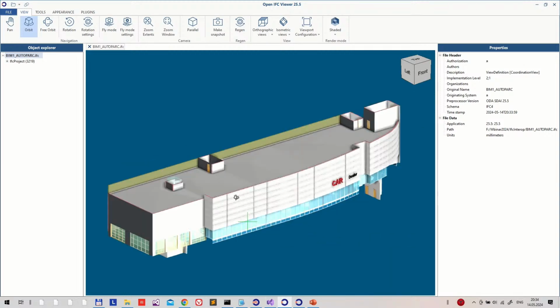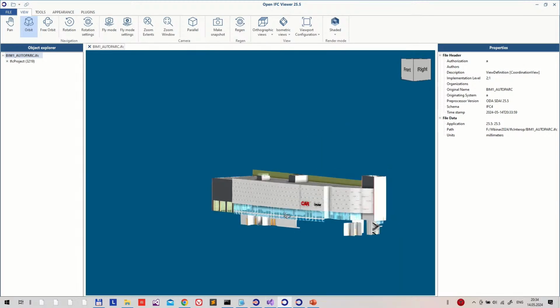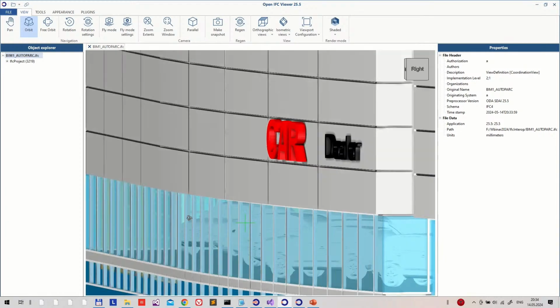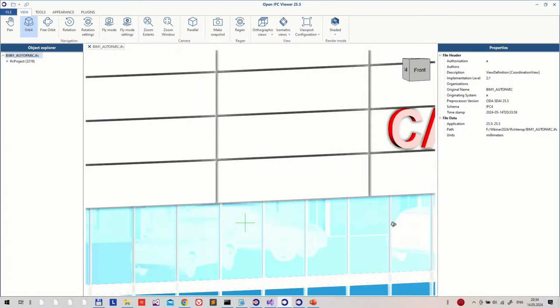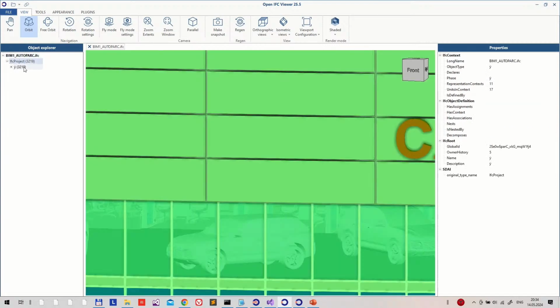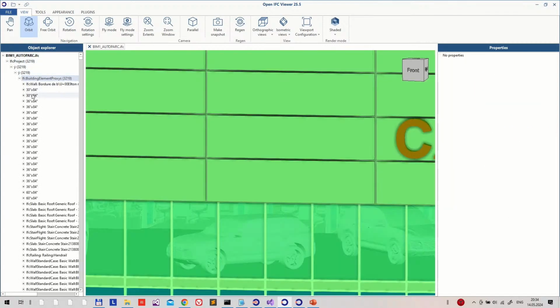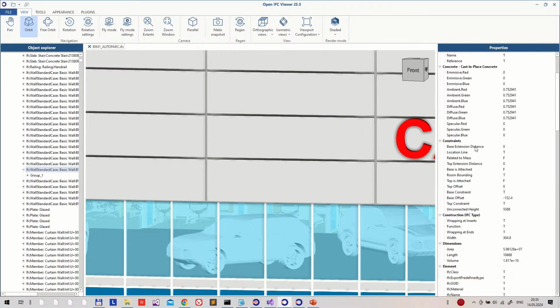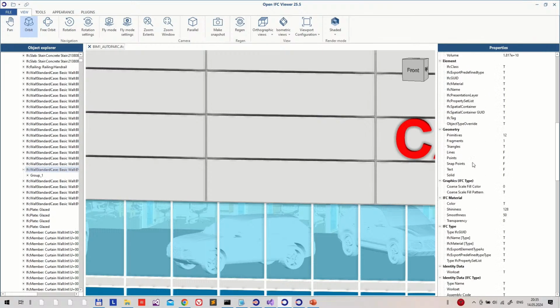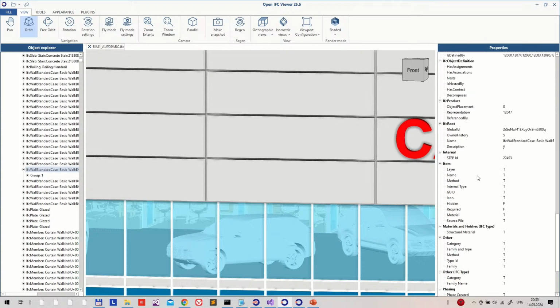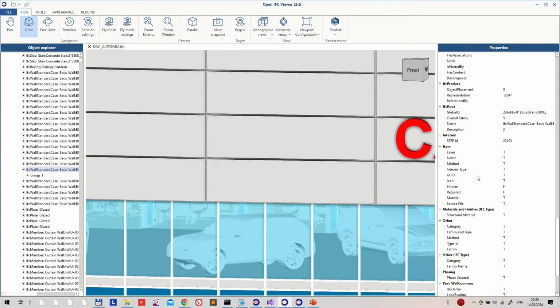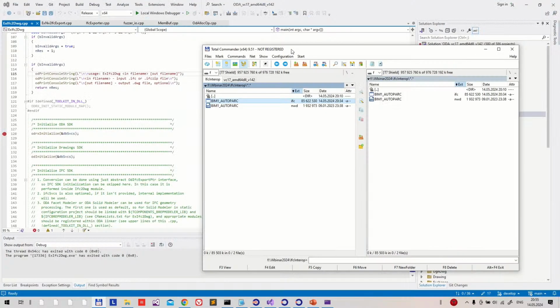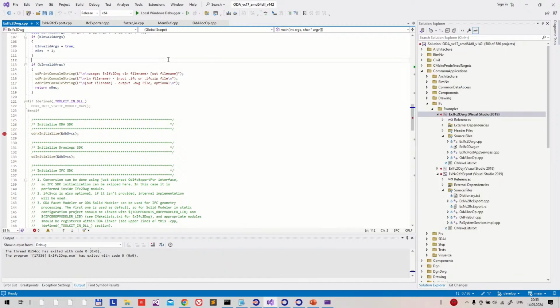That is what we received for the IFC model with the current implementation. As you see, those are not just geometry primitives in IFC or some primitive elements. Those are complex elements, and what's more important, you can also customize the mapping of the NWD model elements to IFC model elements.